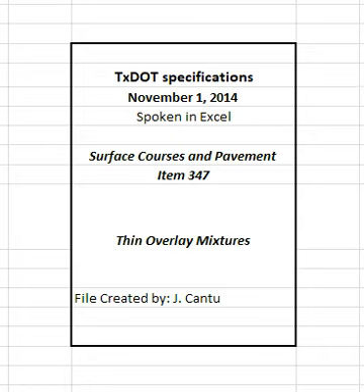2.2 Mineral filler. Mineral filler consists of finely divided mineral matter such as agricultural lime, crusher fines, hydrated lime, or fly ash. Mineral filler is allowed unless otherwise shown on the plans. Use no more than 2% hydrated lime unless otherwise shown on the plans. Test all mineral fillers except hydrated lime and fly ash in accordance with TEX 107E to ensure specification compliance. The plans may require or disallow specific mineral fillers.